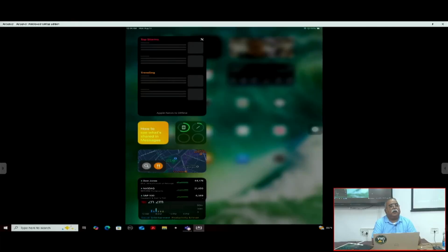Of two sides. On one side, we are getting a response at lower frequency, and on the other side, we are getting a response at higher frequency. The response depends on that side. So when the response is more on the high frequency part, that means the subsurface is much more stiff. Whenever you are getting a response at high frequency, that means it is a very shallow formation, so the soil is very thin.